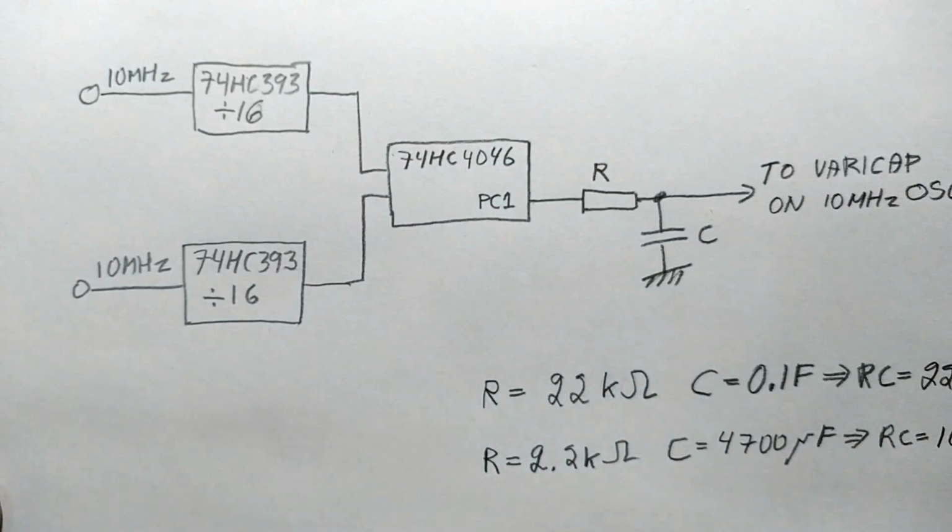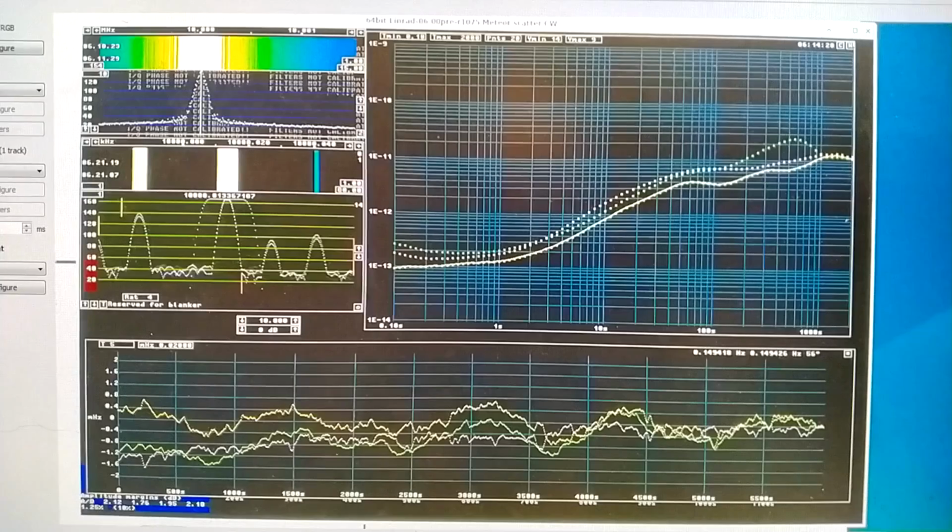I have made a measurement using a very long time constant, 22 kiloohms and a capacitor of 0.1 farad. That gives a time constant of 2200 seconds. I will show a little bit what the results of that were.